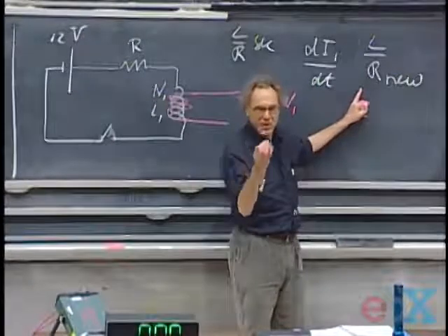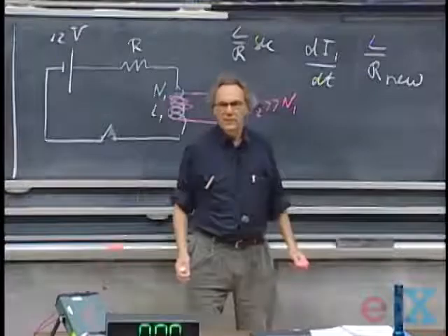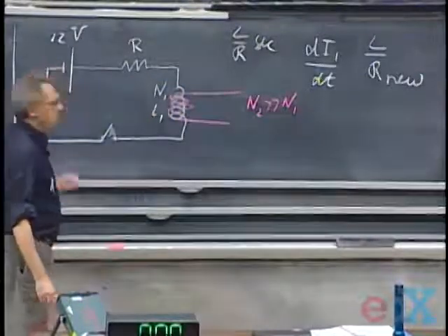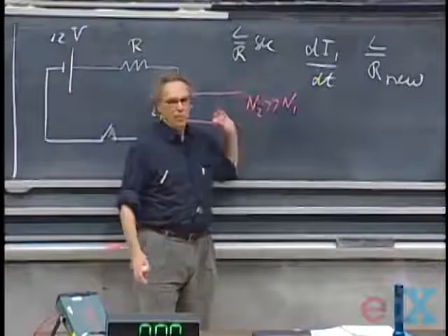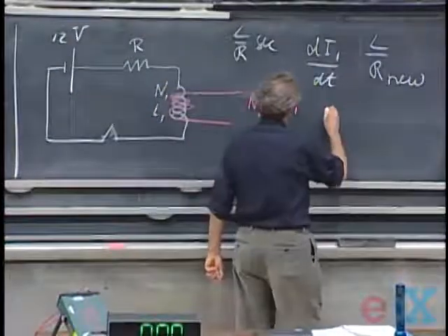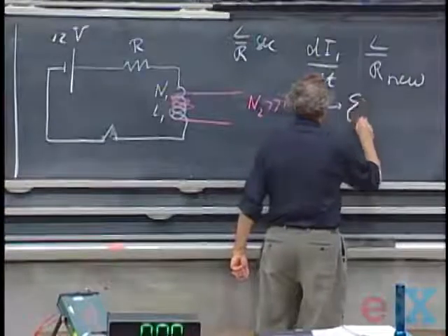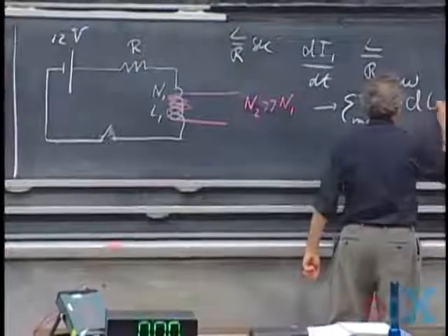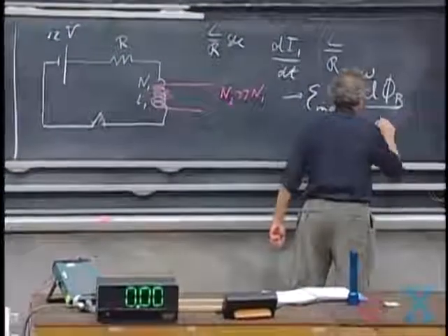So that makes you see indeed why the dI1/dt becomes enormous. With a 12-volt battery, you can easily get several hundred volts EMF now, because the dI1/dt will, of course, create an EMF, an induced EMF in that circuit, because you get a dΦ/dt.